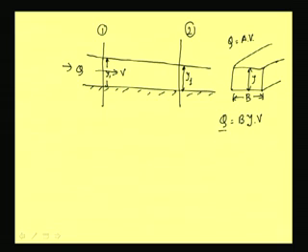When the same amount of discharge is coming, the discharge is not changing all through the channel, and the depth is not changing either, it is y1 here and y1 here. If it is a prismatic channel, b is also not changing, so v will not change. That means if it is v1 here, it goes out with velocity v1 here too, and this sort of flow we call uniform flow, that is, the flow parameters are not changing with distance, with space.